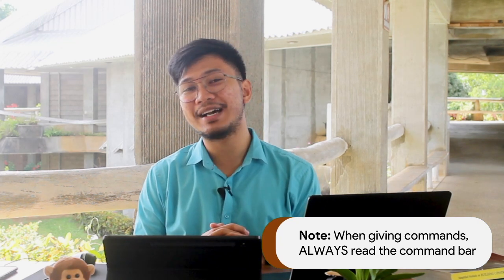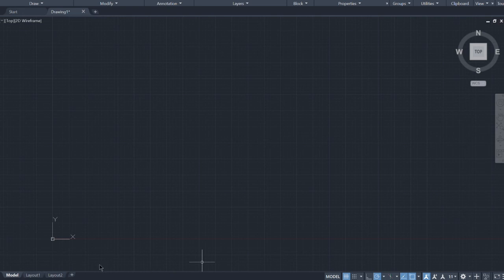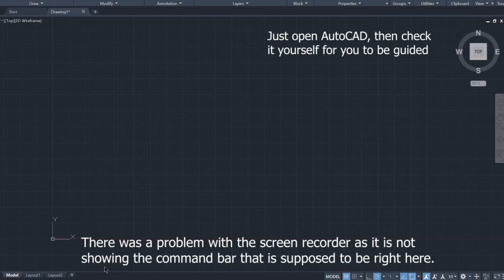I think Ma'am Bea already told you where the command bar is in our AutoCAD interface. And that is this one, right here. Okay? It is usually magnetized at the bottom. That is your command bar. So, whenever you are going to make commands, always look at that bar because there are steps that will be asked of you depending on what you want to do. And that is what we are going to do right now when we draw these 2D objects that I will be discussing to you.